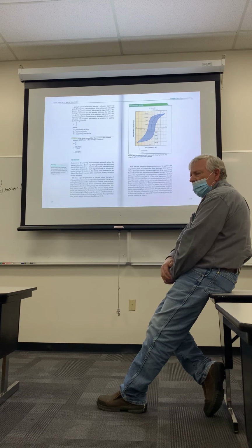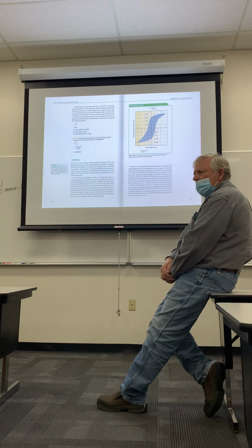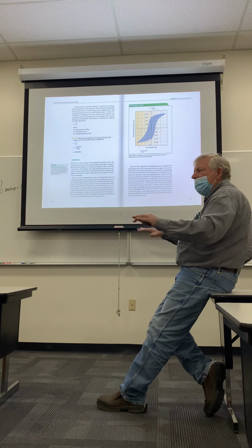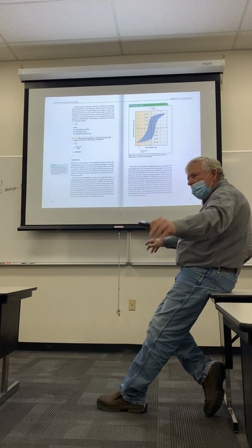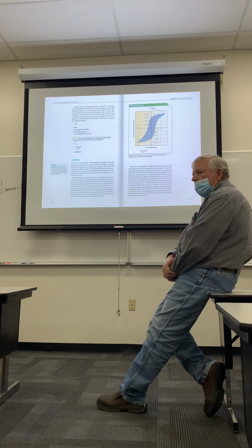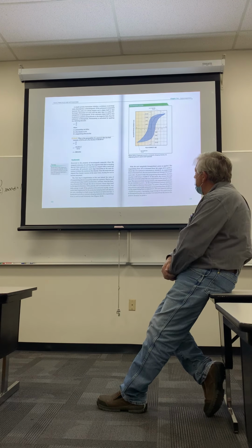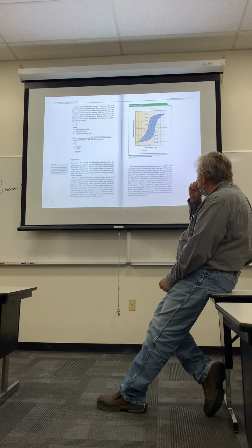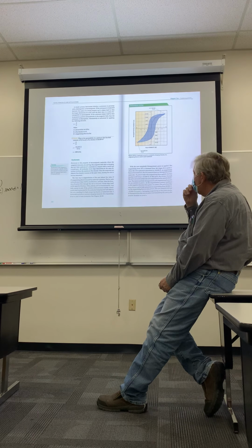So is it the same as retentivity then? Retentivity is a function of it. Different materials have different rates of lag. So hysteresis isn't a relationship between flux density and magnetizing force. It's the lag off of that. Yes, correct. It's the phenomenon that is the property of materials and their rates at which they magnetize and demagnetize. And this is just a sort of a generic curve that we're looking at here.